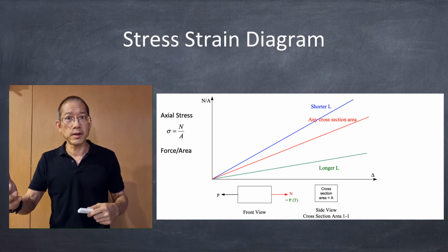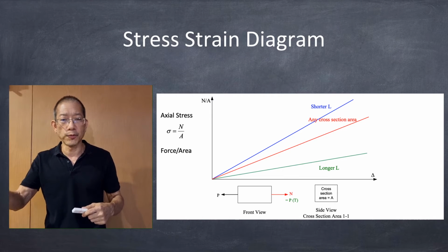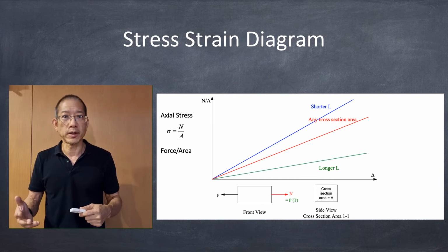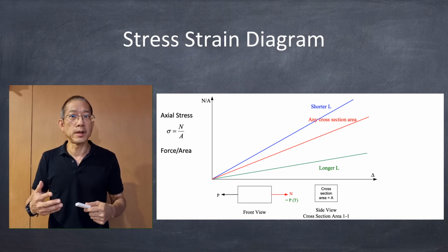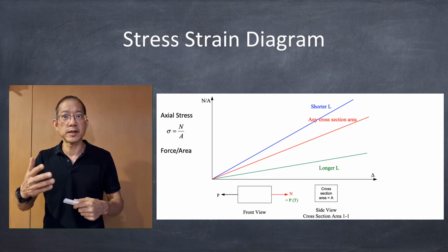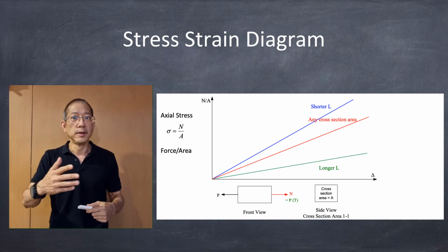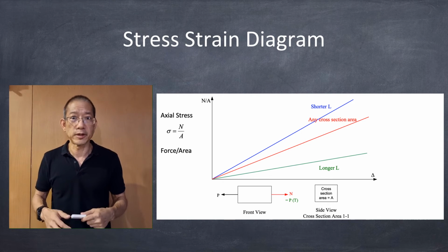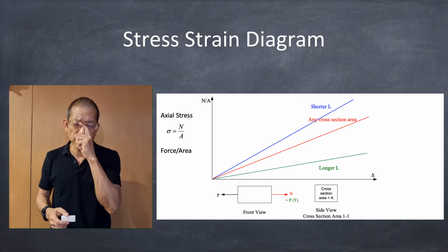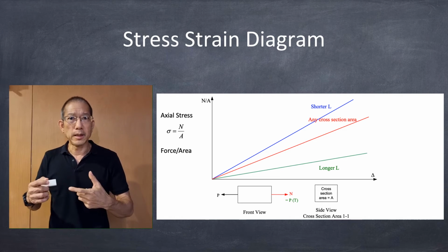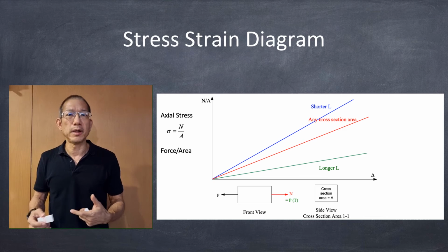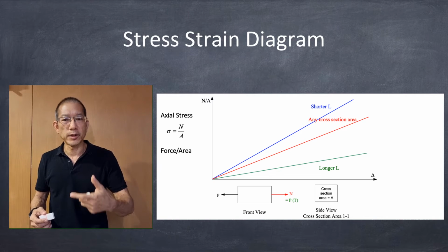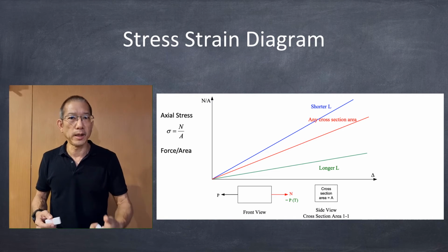So they said, well, let's talk about a new variable called stress, right? Which is the symbol we usually use for the normal stress. In this case, as I said, it's normal stress or axial stress. It's usually denoted using the sigma, the lowercase Greek sigma, right? And it's averaged all over the area. So they try to average over the area. So they use N over A, right?